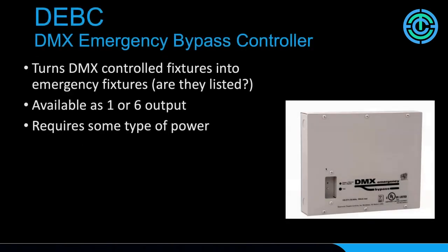Talk a little bit more about emergency in a moment. One of the lighting specific devices that ETC makes that has to do with emergency has to do with the fixtures, mainly architectural fixtures that have come out over the last number of years. Fixtures have moved from being line dimmed fixtures to 0 to 10 control fluorescence, 3-wire fluorescent to our LED adoption.